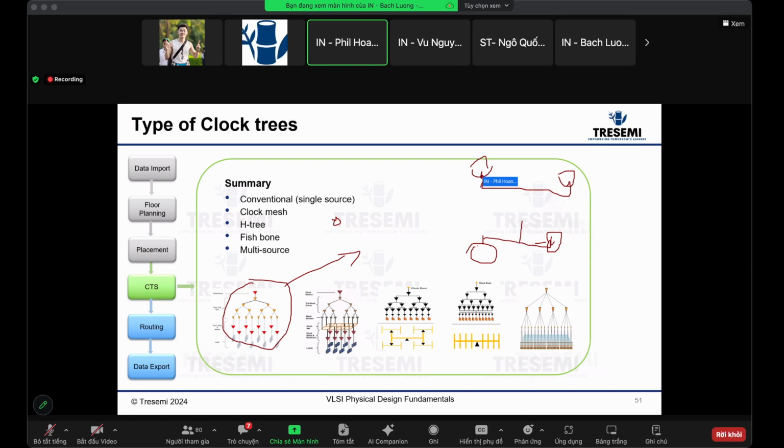So when you wire here, it will wire to the midpoint of this H3, and this H3 will split out very evenly like that. Right, so that's the key point you just touched. This tree has to be balanced. These wires have to be equal. Okay, these have to be balanced. So instead of relying on the tool to do RC matching, you actually build the RC matching wires to guarantee it.